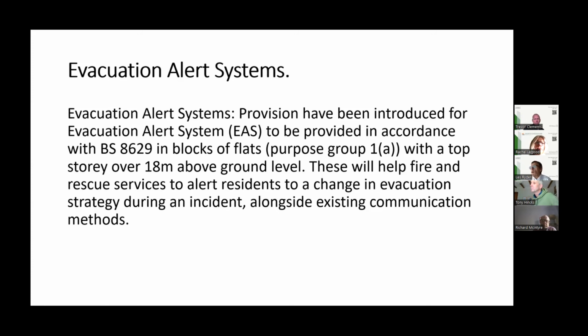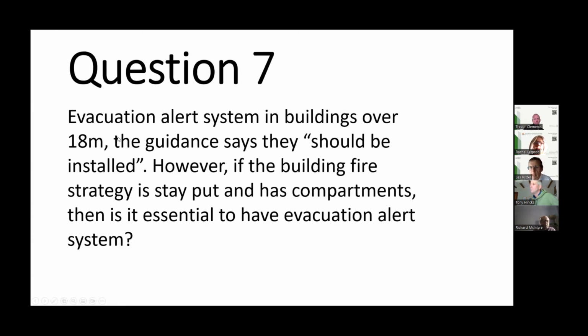What we've always assumed is that the compartment will protect us. The principle is that if you're in the flat that catches fire, you leave that flat, you escape from that flat. Whether you alert the neighbours or not is entirely up to you. If any smoke gets into the common corridors, that will activate the smoke control system, but it won't raise an alarm. And so the only way that anybody will actually know there's a fire in the building is if they can hear the unit where the fire is actually taking place.